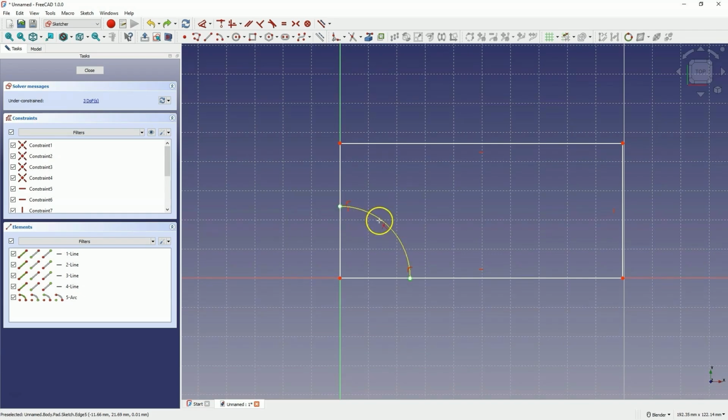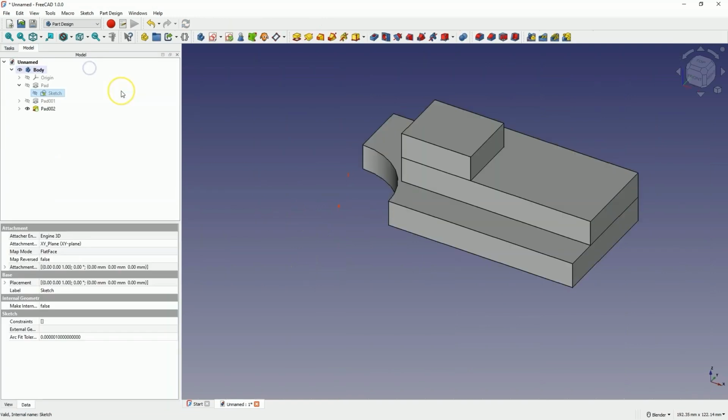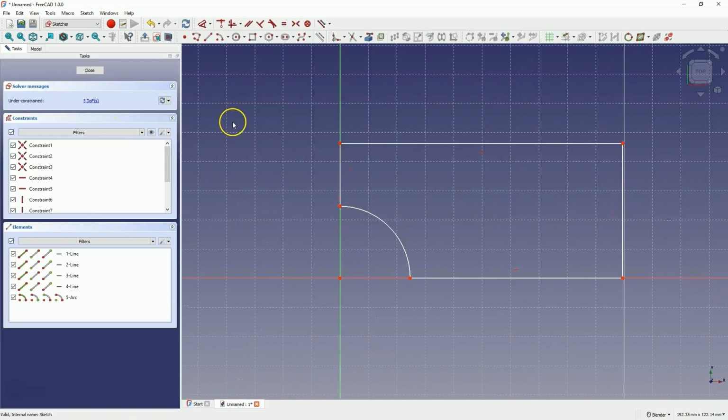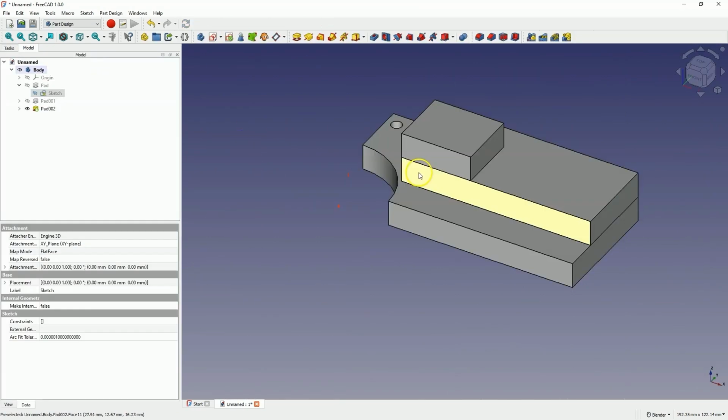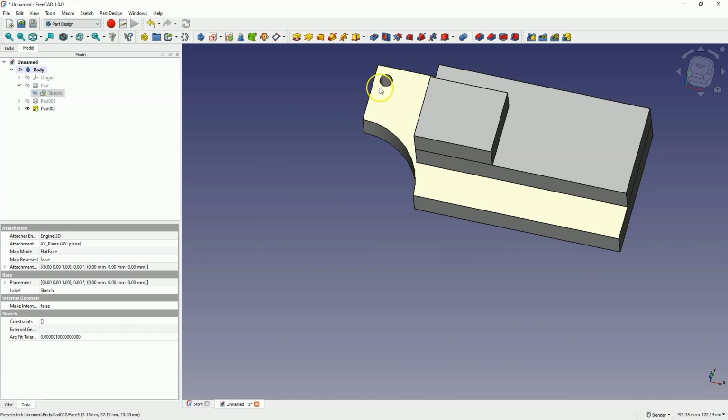It looks like this, but if we trim something and the drawing appears to be trimmed too much, usually when we press Ctrl Z, we return to the point where that trimming looks correct. I close the sketch and now everything works correctly on this model. In this version, we can indeed make such changes. I will edit this sketch again and draw, for example, a circle here. I close the sketch and a hole based on that circle has been created here.